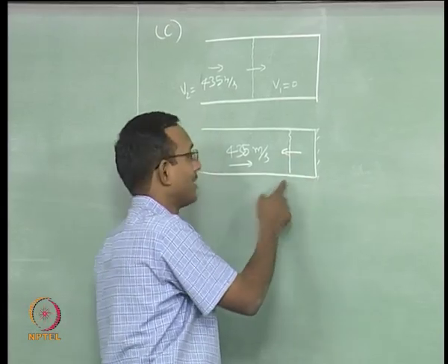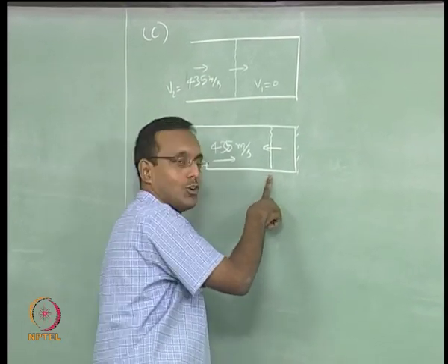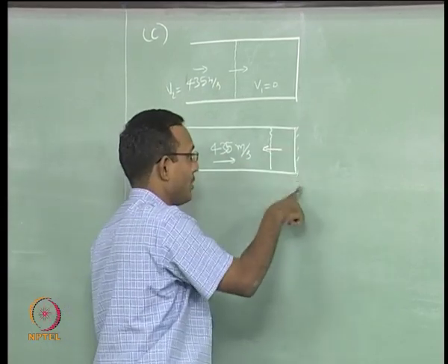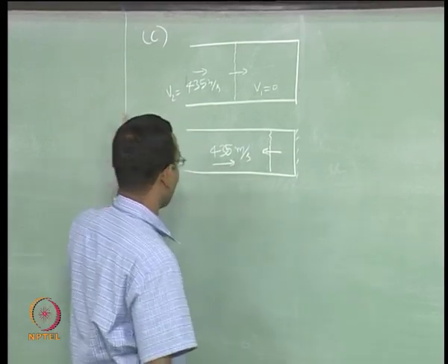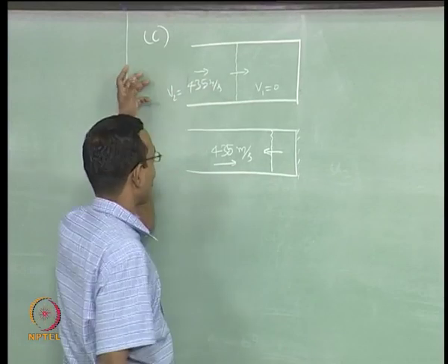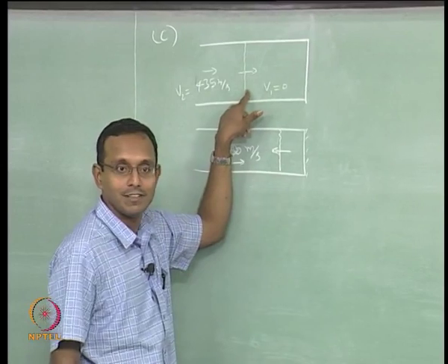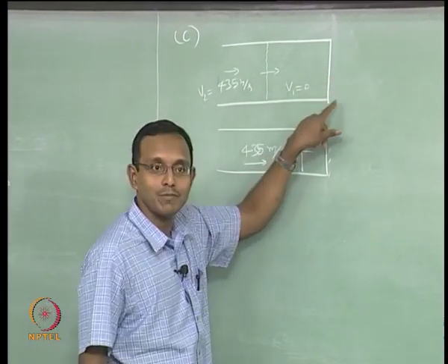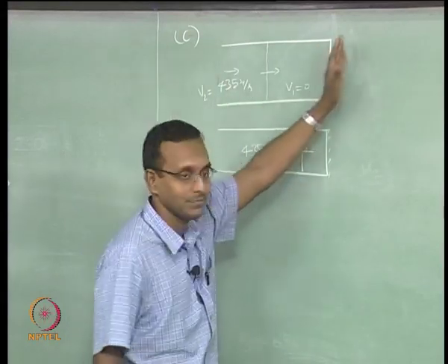This is what they call the reflected shock. This shock's job is to go and tell every fluid that is coming this way that there is a wall, you cannot move this way. All the molecules, we will go back to molecules, thought there is a lot of space, they are all coming this way. When this shock went here, till that point there was no information about this wall to this fluid. So, they all kept coming.